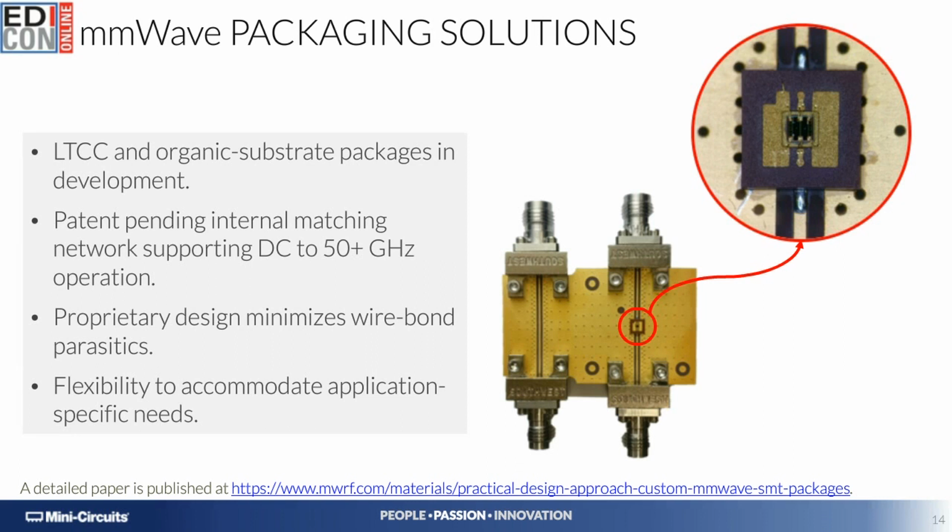We're discussing today the LTCC approach, but I would like also to inform you that we have a soft substrate version of the same. These packages are intended to operate above 50 gigahertz, and we have test data that supports that viability.